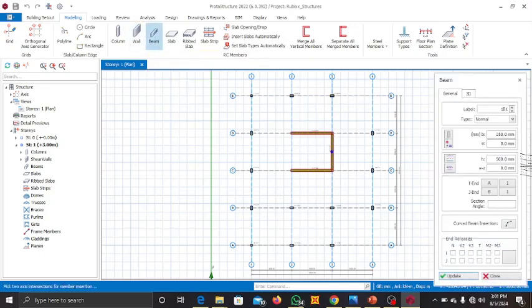So click on the beams on the ribbon. You see the letter type. We are going to use a normal type of beam. But if you click the drop down menu, you see a wall coupling, but we're going to use a normal type for beam. This B is the breadth, like how wide is your beam. So we're using a 230 wide beam, and the depth of your beam, let's use a conventional 450 depth. Okay, this is for the member section.